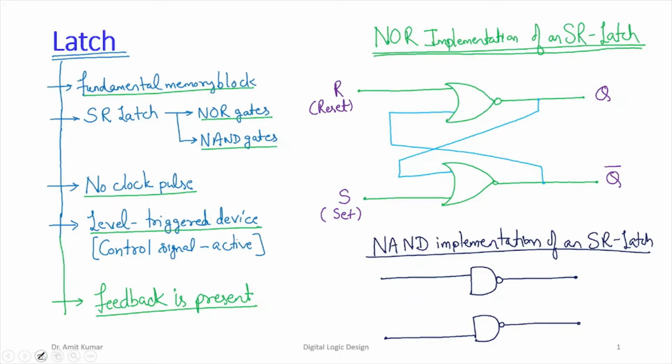Next, since this is a latch, definitely there is going to be a feedback mechanism. The feedback from the output terminal will be connecting to the input of this NAND gate. Similarly, the feedback from the output will be connecting to the input of this NAND gate.